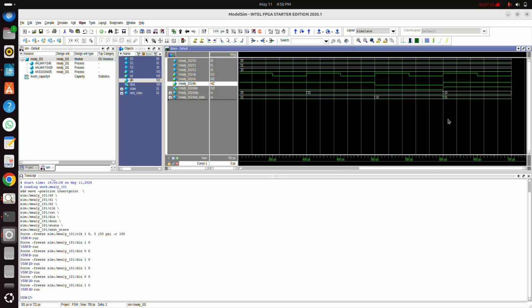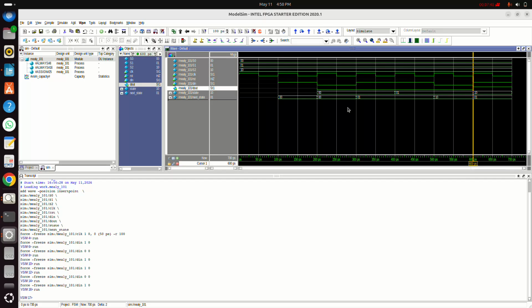And we can see here our output goes high according to the code logic. Okay, now I will explain in the wave what happened. As I said, at the starting edge of the clock we do not provide data input or reset, so it is in a high impedance state, so our outputs are don't care. Okay, so it starts from this edge of clock and we can see our sequence.